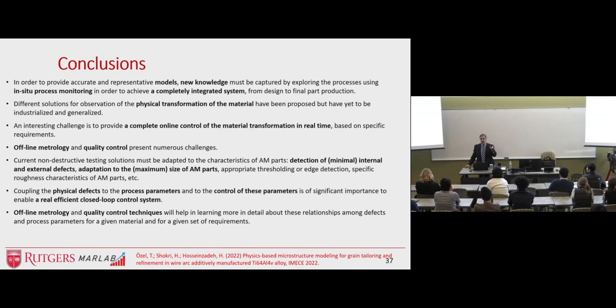So quick measuring techniques are in dire need in order to see layer-wise, not just layer-wise, track processing, as well as once a layer is finished. A lot of machine tool companies developed a really quick assessment of their layer builds, either by fringe projection or optical tomography, so that they can see what's on the layer. You cannot see what's under the surface. And putting a computed tomography type of device into a powder bed fusion machine is too expensive.